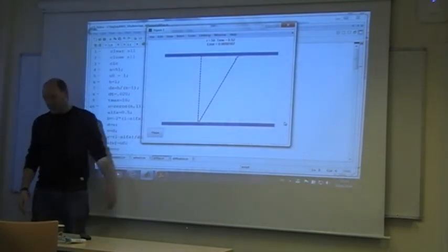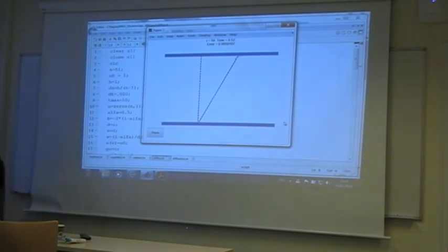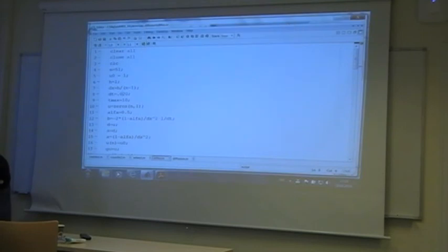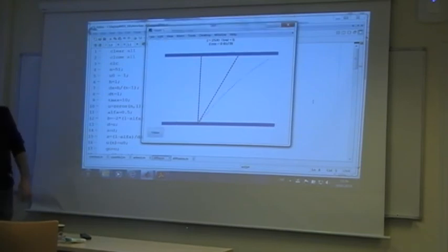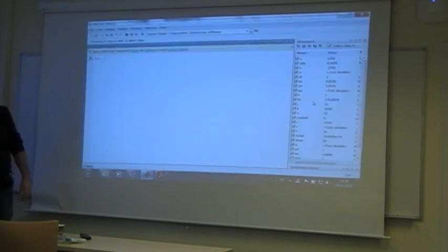So using a partial implicit scheme, you don't do it if you really want to have the correct time behavior. If I increase it even further, I can have a time step here of 1. It's still stable, but it looks really, really stupid. So no, this is not a good idea.